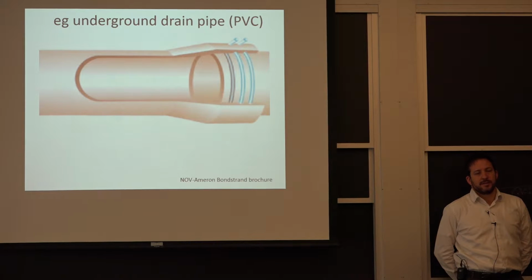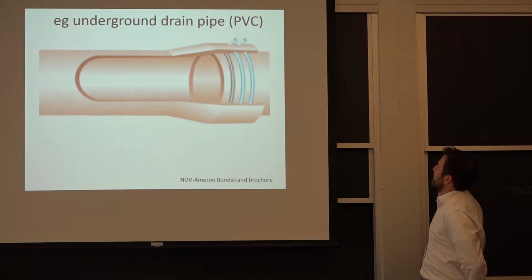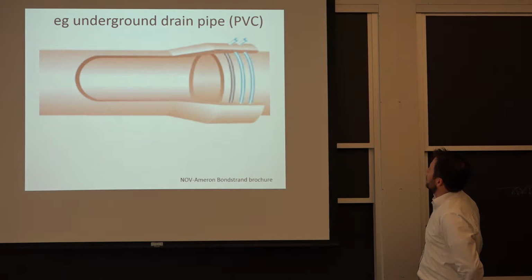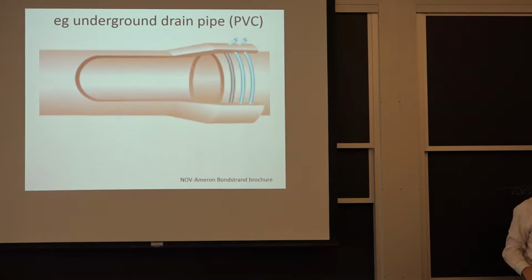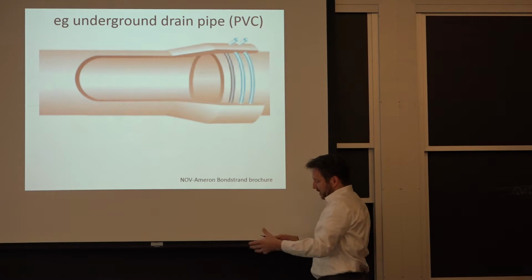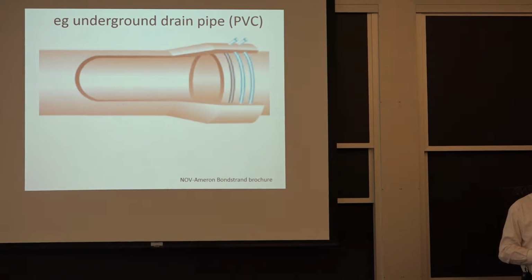Yes? What are the two pieces sticking out? Yeah, that's a good question. I say just ignore it because this is really just an O-ring going all around. I don't know why. I haven't come up with the image. They probably have always been there. Good question. But this goes to the outside, and it's a bigger diameter, and then you insert the other piece in it. And the only reason for three O-rings is redundancy. In principle, you could have just one.